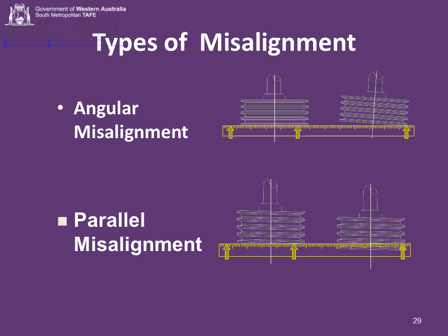Wide synchronous belts are more sensitive to angular misalignments than narrow belts. Parallel misalignments also result in accelerated belt and sheave wear and potential belt instability. Uneven belt and cord loading is not as significant a concern as with angular misalignment. However, parallel misalignment is typically more of a concern for V-belts. Parallel misalignment is generally not a critical concern with synchronous belt drives as long as the belt is not trapped or pinched between opposite flanges and as long as the belt tracks completely on both sprockets.